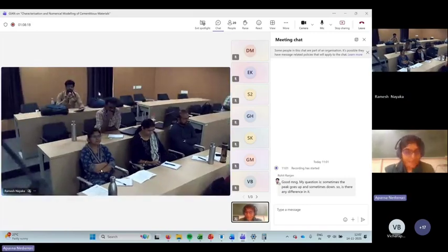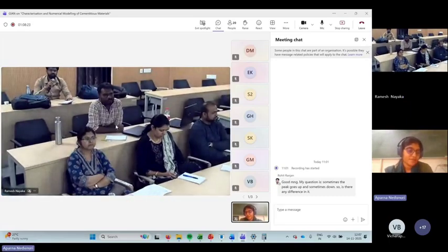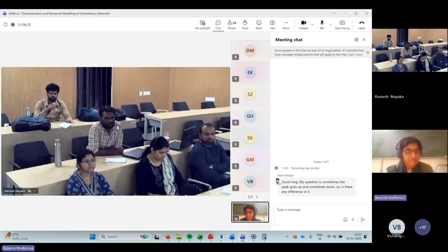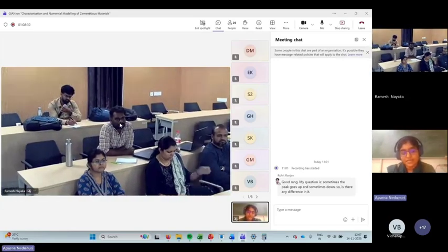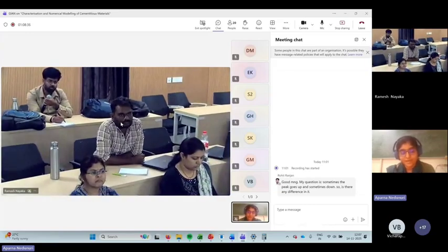If it is unreacted, it means we do not have any unhydrated product. So you can always run a TGA on the raw material as well, and then deduct that raw material TGA from your hydrated material TGA to get the amount of hydration products. That is one way to look at it.